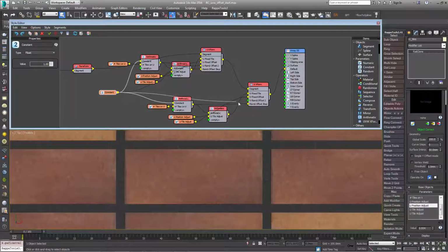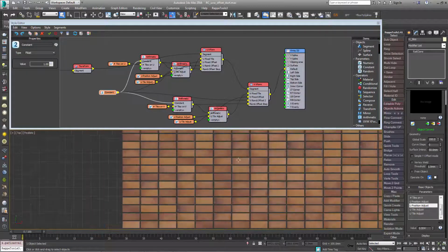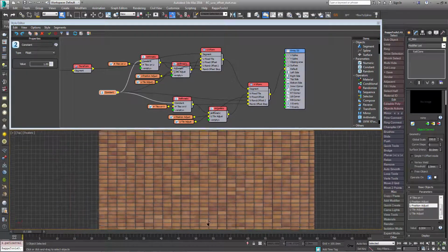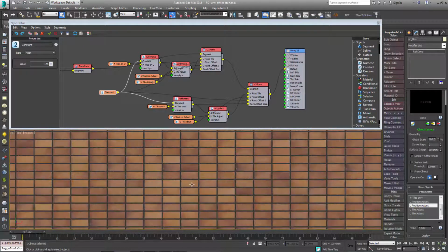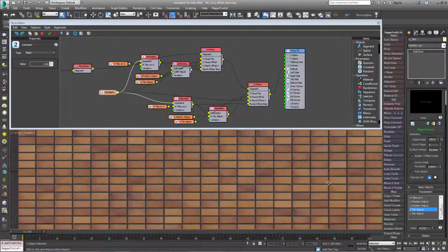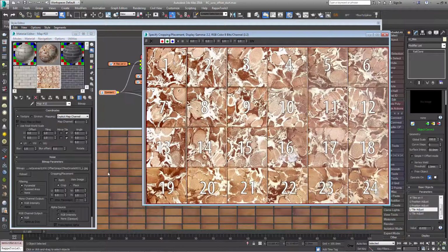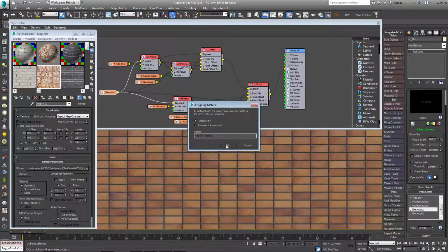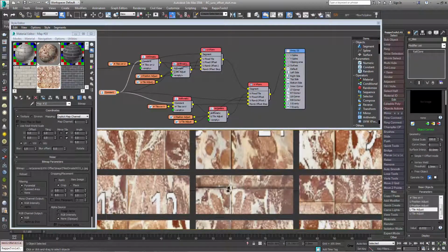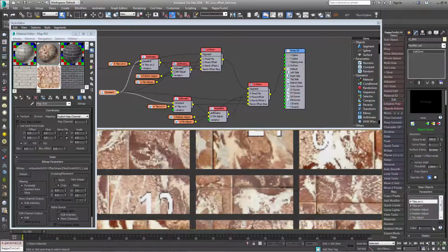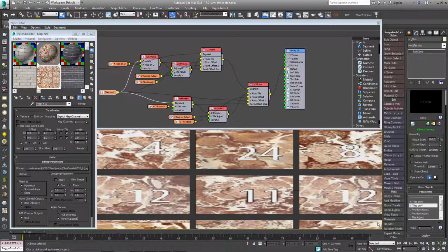And if you followed this successfully, you'll now have a style that allows you to add a bitmap with tiles or bricks in a stack bond pattern and extract individual textures, with controls to adjust the offset and scale so that you can clip out the grout or mortar. If you want to check it works, you can apply a different material, making sure you adjust the number of tiles on U and the number of tiles on V values to match the new texture. The segment's UVs should be automatically recalculated to match the new bitmap.